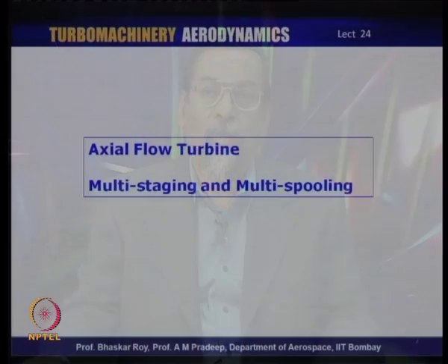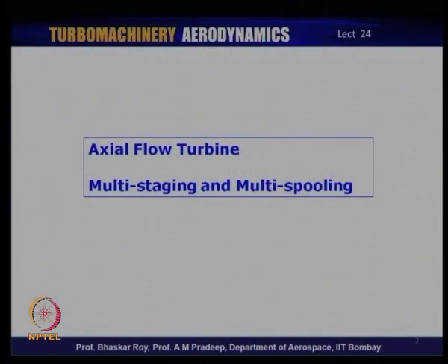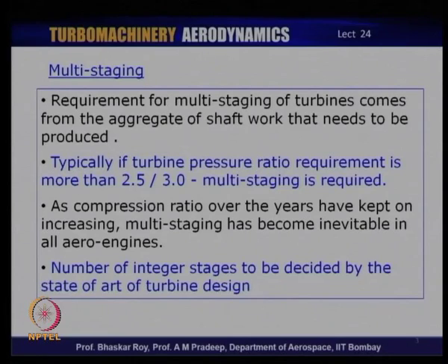Let us look at some of these fundamental considerations that go into the adoption or selection of a multi-stage configuration for axial flow turbines. So, the considerations that normally go into multi-staging and multi-spooling, to begin with, let us look at the multi-staging requirements.